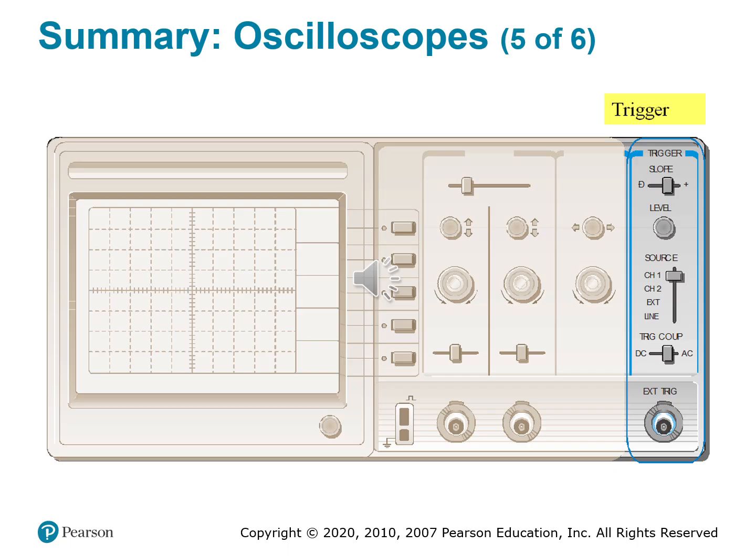Quite a bit. Okay, I think we're almost done here. The trigger coupling, right? The AC and DC. This controls what part of the signal is used for triggering. AC coupling filters out DC offset and focuses on signal transitions. DC coupling uses the entire waveform, including those DC components. And this is useful for rejecting noise or zeroing in on waveforms.